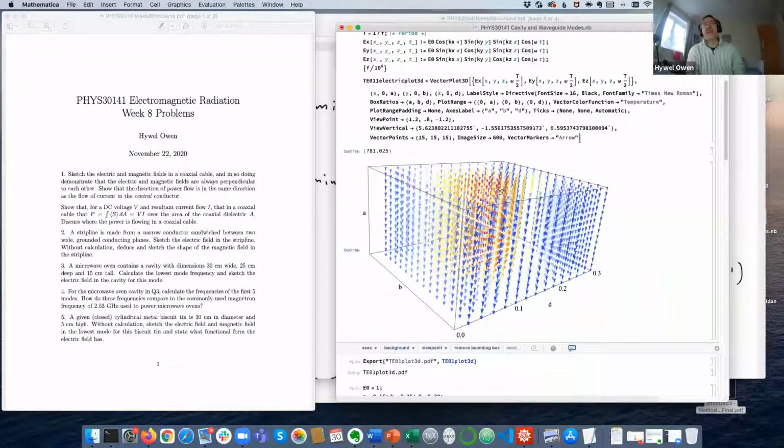Now, in reality, we use a magnetron of a higher frequency. So if I fed microwave power at this frequency only, it would couple into this mode. But if I fed it at a slightly different frequency, then there would be some sort of mismatch, and I wouldn't effectively couple power into this particular mode.